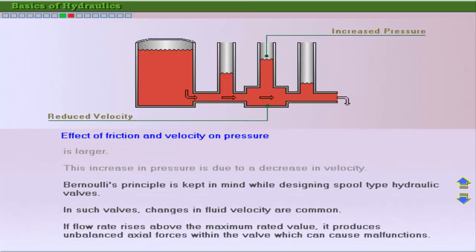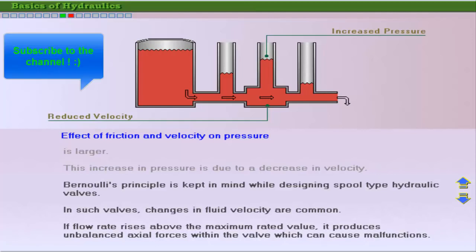When designing spool-type hydraulic valves, it is important to keep Bernoulli's principle in mind. Here, changes in fluid velocity are common, and if the flow rate is allowed to go beyond the maximum rated value, unbalanced axial forces arise within the valve and it malfunctions.